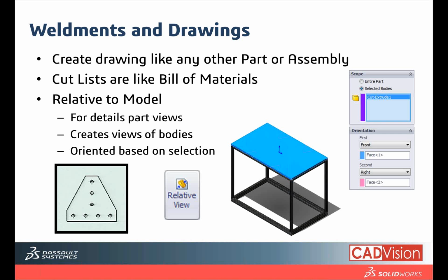Then we will go into the drawing view, drag in your drawing view and call out the cut list, customize your cut list, and then put in auto balloons to show which of the parts belongs to which column, which row of information. And if there are any hidden parts, you can always click on the relative views to call out these hidden parts. This relative view will serve the same as the drawing view, where you can configure the size, the scaling, and the display view of it.